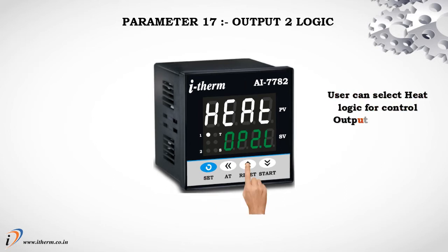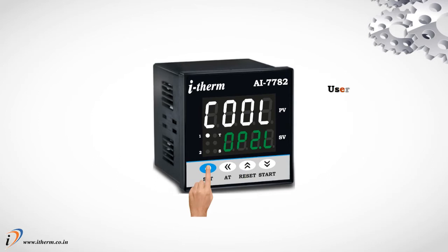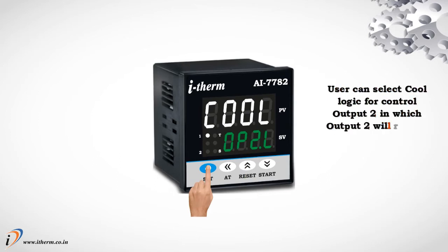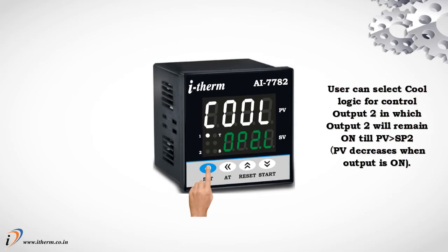Parameter 17, Output 2 logic. The user can select heat logic for control output 2 in which output 2 will remain on until process value is less than setpoint 2. The user can select cool logic for control output 2 in which output 2 will remain on until process value is greater than setpoint 2.